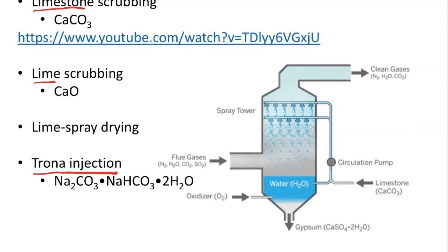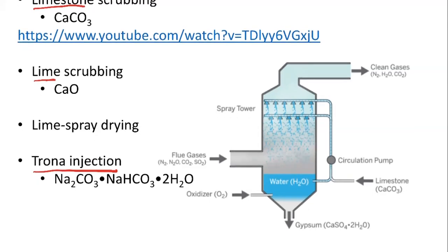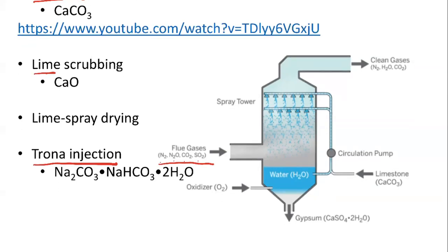So what happens is we're going to introduce flue gas from the bottom of this scrubber. Okay, the flue gas can contain, as we mentioned, nitrogen, carbon dioxide, sulfur dioxide. We may also have some nitrogen oxides in there. It really depends on whether we remove these nitrogen oxides beforehand. Okay, so the flue gas is going to be introduced here, and this is the outlet. Okay, so as you can imagine, the air will just go upwards, right?